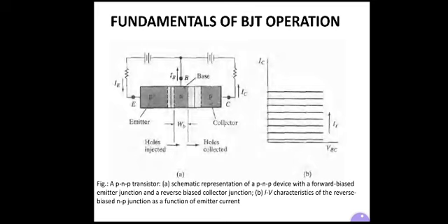To understand a good PNP transistor, we would prefer that almost all the holes injected by the emitter into the base will be collected. Therefore the N type base region should be narrow. As you can see from the figure, the N region of the base is very narrow, and the hole lifetime tau p should be long. The hole lifetime, denoted as tau p, should be very long. This requirement is summarized by specifying WB, as shown in the figure.